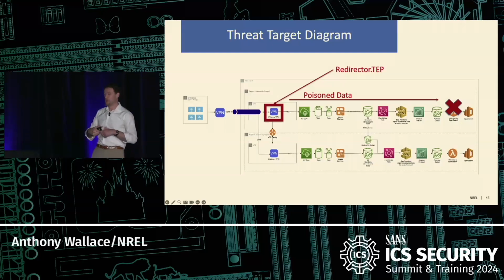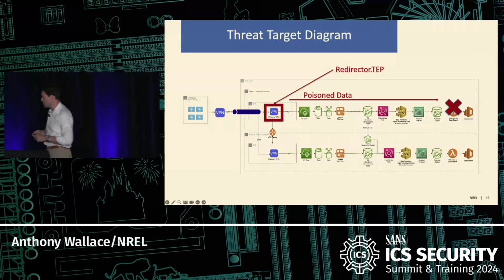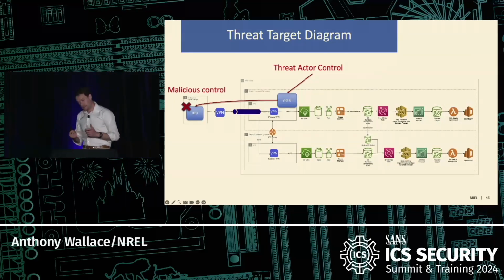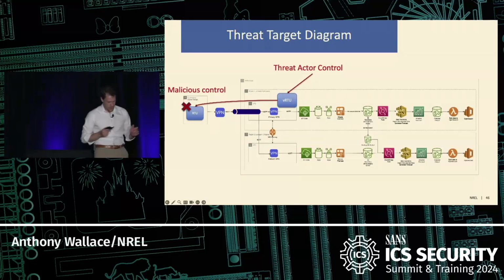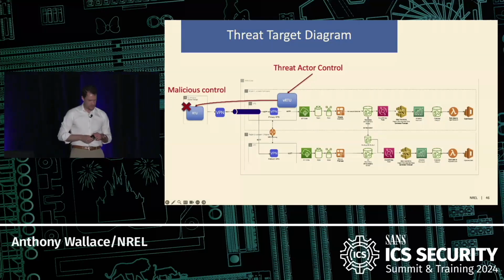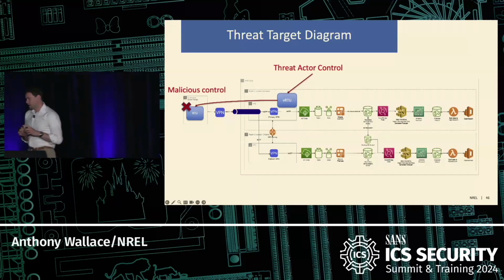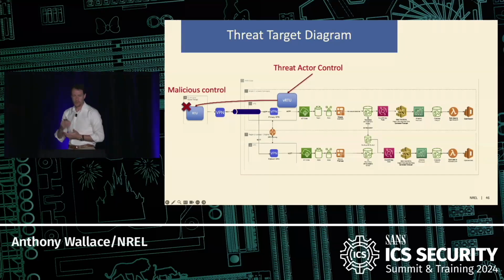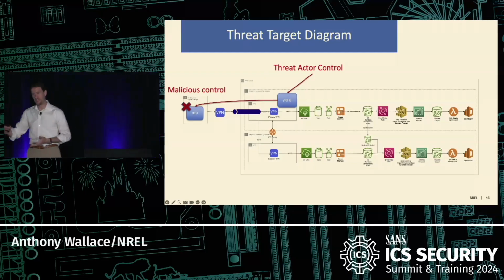And so that's the opposite direction, where you are not underreporting what you actually have inside of your system. So we tried this class of attack, and we also tried this control class of attack. So we have a system at NREL, again, developed on previous systems developed at Sandia, called OTSIM, the Operational Technology Simulator. This is a modular system that is architected to operate like a PLC. There's a pub-sub backplane that you can write modules for. You can write them in Python or C++, and those modules are either communication modules or modules that interact with the Helix system to allow us to affect change in the power model.